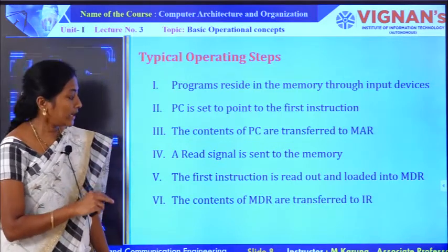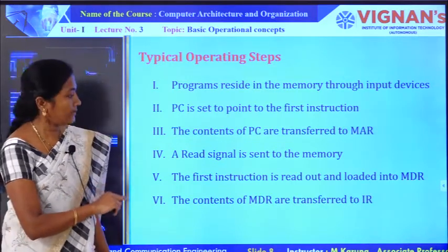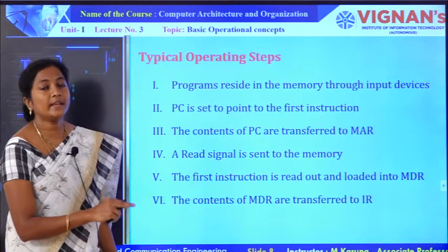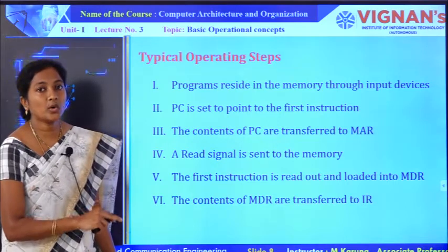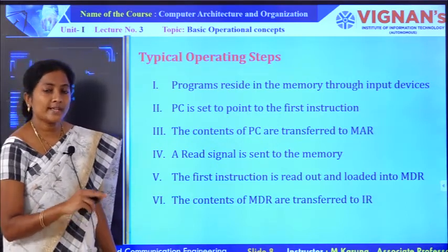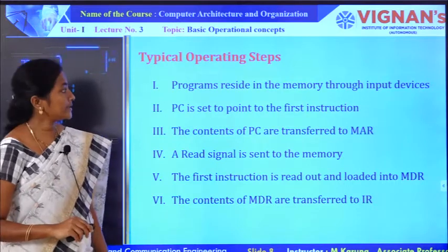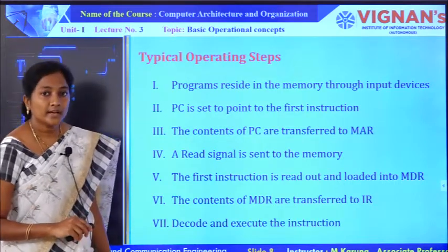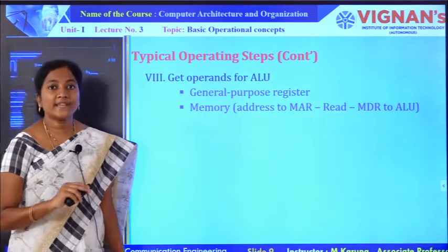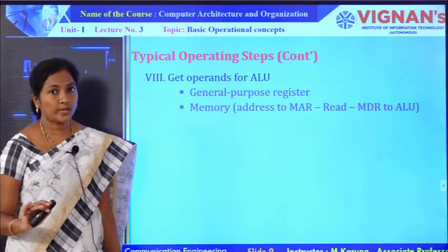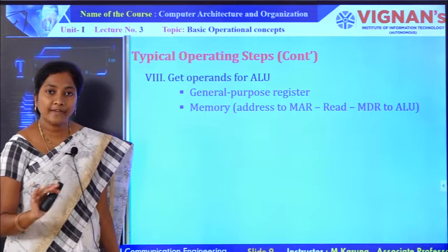Next, whatever the loaded data in MDR is transferred to IR. Here the data is the instruction code. Now the instruction code is stored in the instruction register. Then decode that add instruction. Now fetching of instruction is over. Coming to fetching of data.